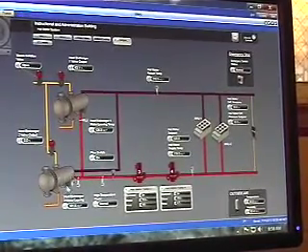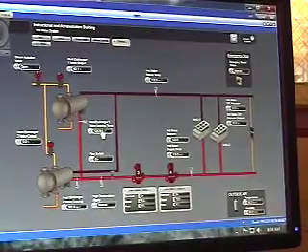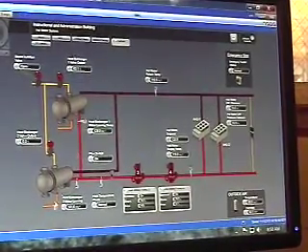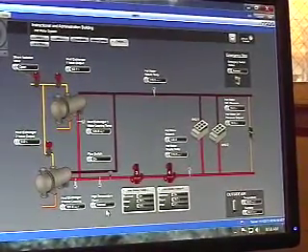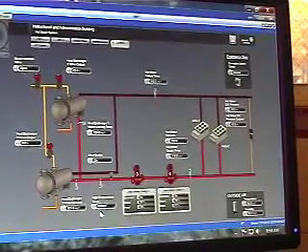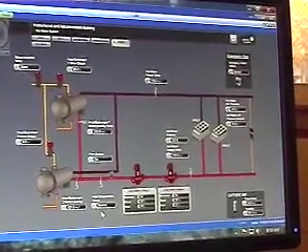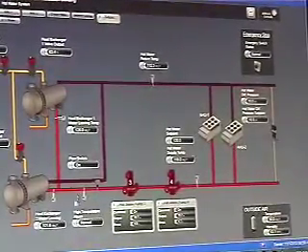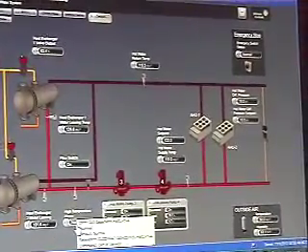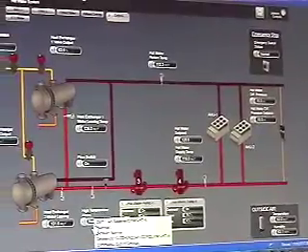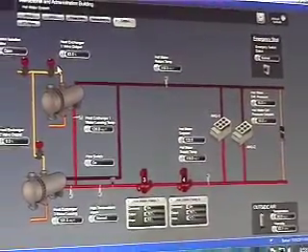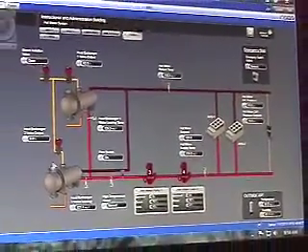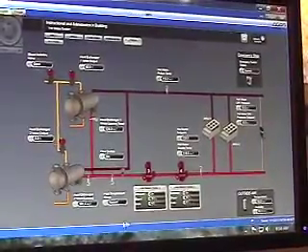Going out of here, these are just for monitoring purposes, what your leaving temperatures are coming out of the heat exchangers. This is your high temperature alarm that we talked about in the building, where it's a manual reset up high. It's set up, I believe, 200 degrees, so if something goes haywire and this trips, it is a manual reset, and it does mechanically force these valves. It loses power to them, and they will force shut.